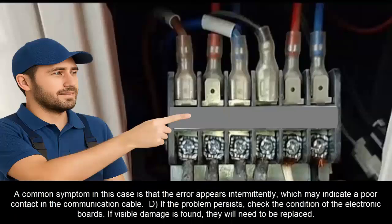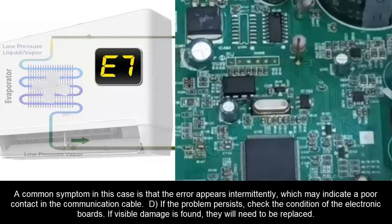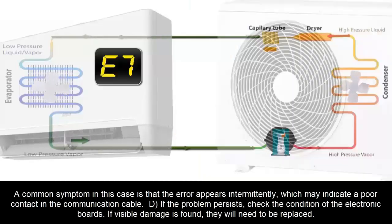A common symptom in this case is that the error appears intermittently, which may indicate a poor contact in the communication cable. D. If the problem persists, check the condition of the electronic boards. If visible damage is found, they will need to be replaced.